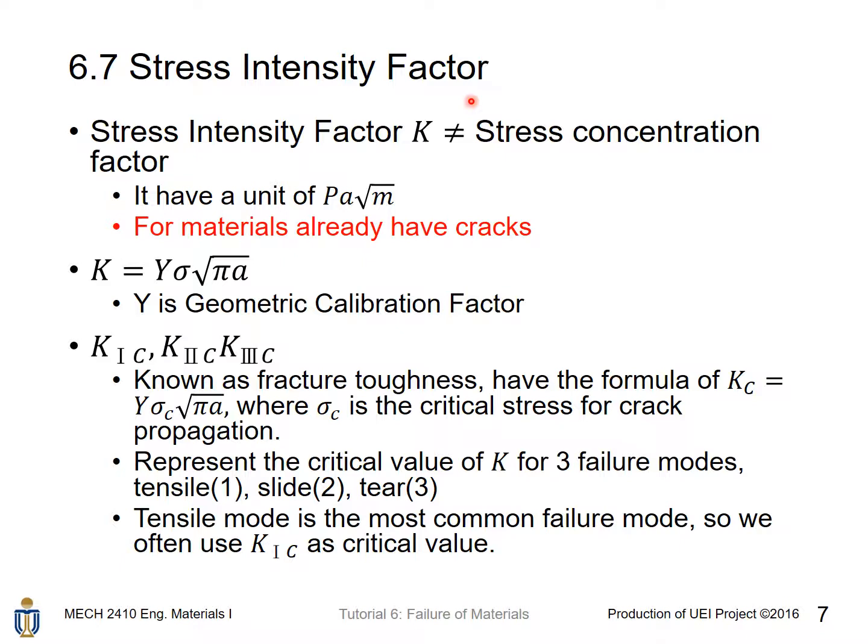However, tensile mode is the most common failure mode. So therefore, we often use K1C as the critical value for a typical material in the design problem.